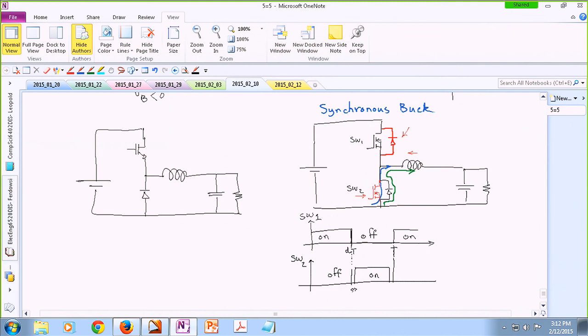And when it is on, the MOSFET wins the competition from the diode, and then your conduction path is the blue path. So your current for most of the time is passing through the bottom MOSFET. Therefore your losses are minimized. Then when you get towards the end, you have to do the same thing. You turn this MOSFET off, so you block this blue path of conduction.